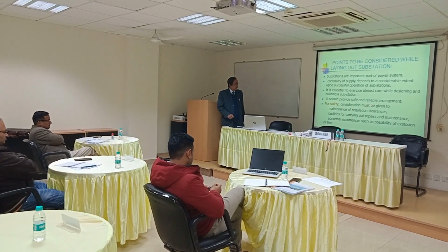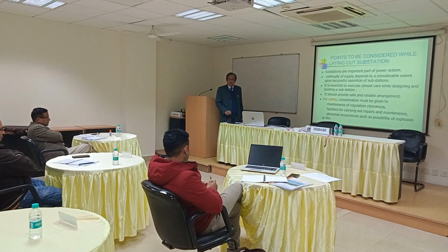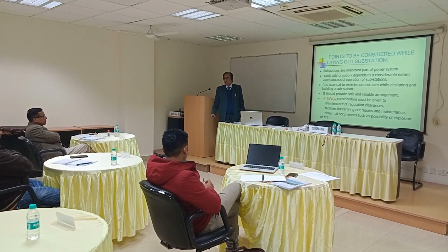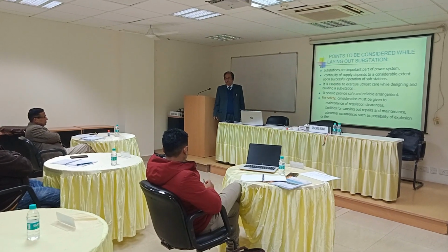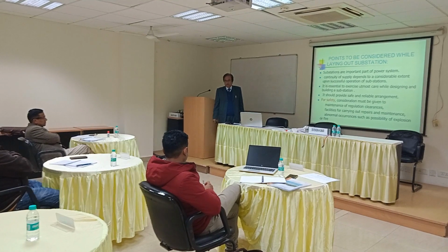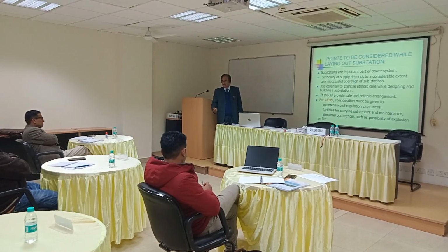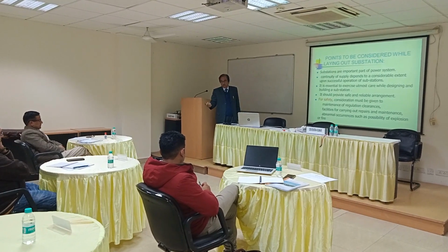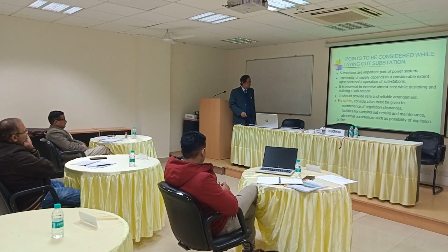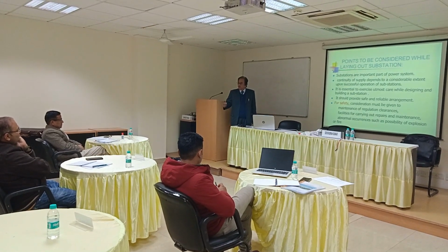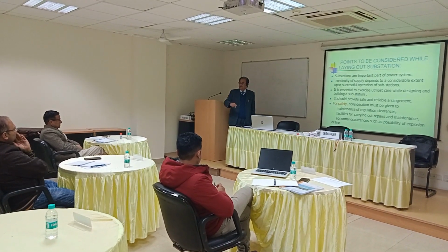For safety consideration and maintenance, we have to provide regulatory clearances from one phase to another phase, and from phase to ground. Working clearance, or what we normally call safety clearance, we have to provide so that the worker can safely do the maintenance work.